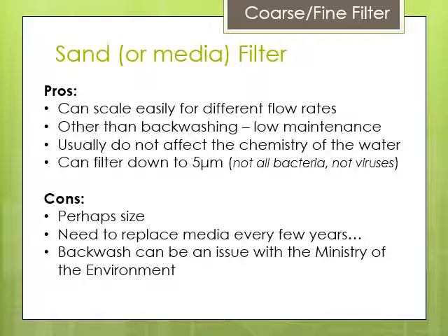I know for our hydroponic lettuce, we use sand filters for our primary filtration, and then we used ozone for sterilizing. But yeah, we use sand filters very successfully. They are fairly low maintenance except for backwashing, and a lot of backwashing is actually automatic.